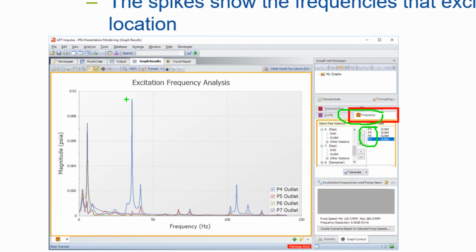When we say OK, if we go to the junction, we see a T for transient. If we open it, we can see the transient in junction 8 and show the graph. Here we have the ring or the strike we applied to this junction to determine the acoustical frequency of the system.